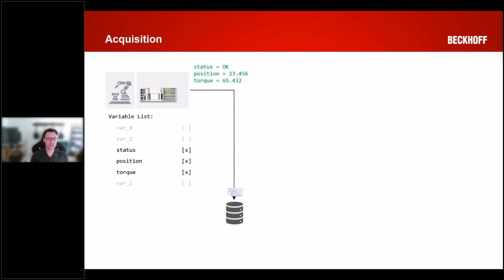Again, this might feel a little bit like the opposite of what many of us are familiar with, where those external systems, your MESs, your SCADAs, tend to pull the data out from the device. But there really are some key advantages to that push approach. Once more, speed and accuracy. If that's a priority, I know that producing that data right from the PLC, right from the horse's mouth, synchronized with my deterministic task is going to be advantageous. I also know that if I run into connectivity issues somewhere along the line, I'm immediately aware and I can begin buffering that data locally so nothing is truly lost.